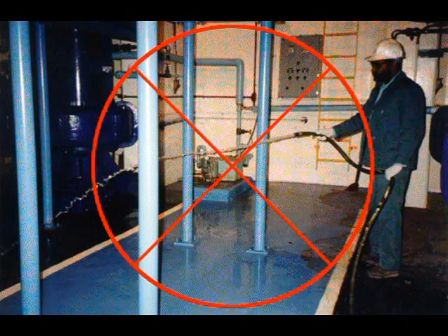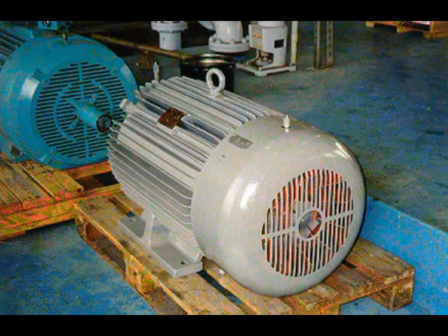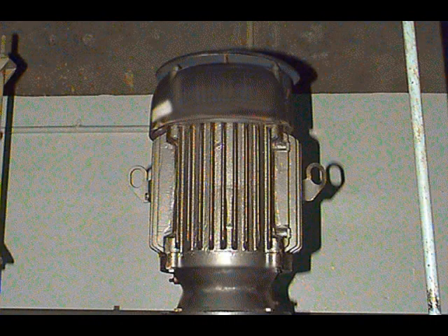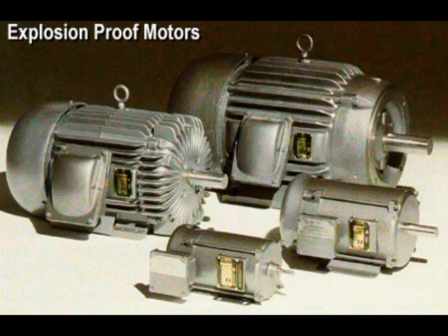Note that both enclosures provide protection from water, but this does not mean that water cannot reach the motor. Even the splash-proof motor can be damaged if it is hosed down. Two types of totally enclosed motors are also common: the TENV, or totally enclosed, non-ventilated motor, and the TEFC, the totally enclosed fan-cooled motor. Totally enclosed motors may also be dust-proof, waterproof, or explosion-proof.